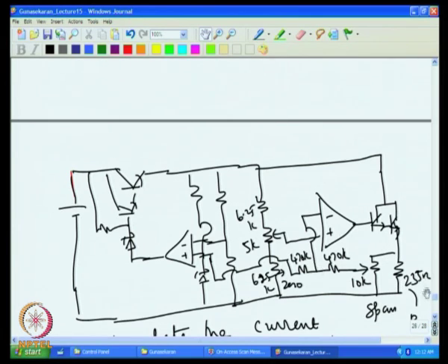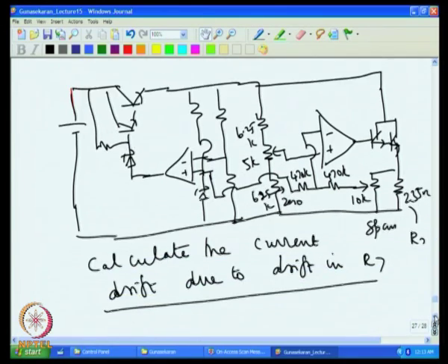We can calculate the current change, and that depends upon the actual current that is flowing. The easiest way of doing this would be assuming that around 16 milliampere current is flowing at the maximum. So, 235 ohm gives you 16 milliampere current, then what current does 1 ohm give? That would be the easier route to find the error due to the resistance change.